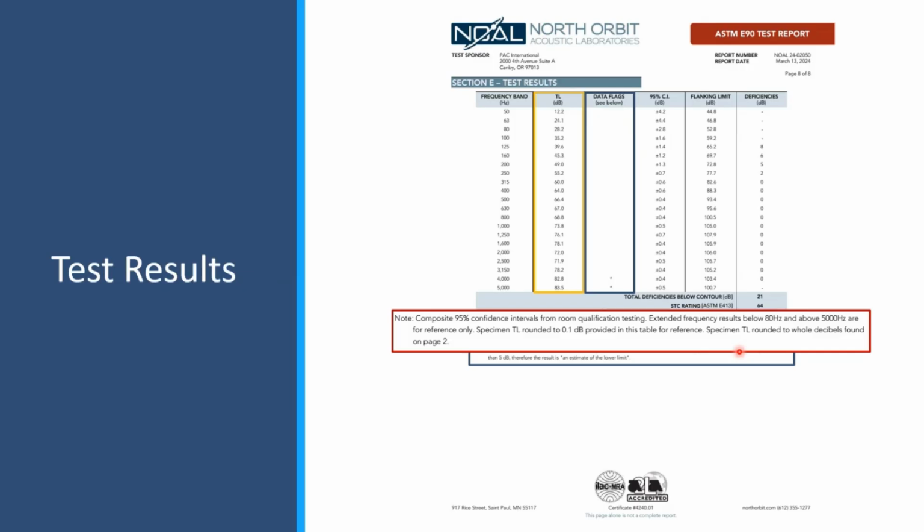And if they are, if they're within 10 dB, I think it is, then you're supposed to put a flag here to say this might be flanking limited, which means that the transmission loss value might actually be higher than is reported. We just couldn't measure any higher, right? And then the last one is a filler wall correction.